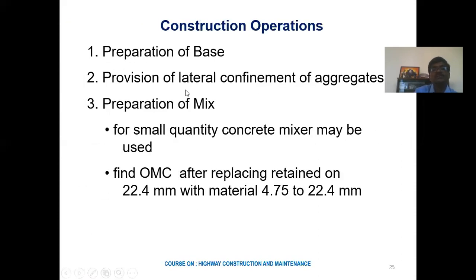So again, the construction steps as per the MRTS specification: preparation of the base layer, that is the receiving layer. The second step is, as I said, confinement is important for wet mix macadam or any granular layer. So provision of lateral confinement, like the shoulders, and erection of curbs in advance is a requirement. Then preparation of the mix.